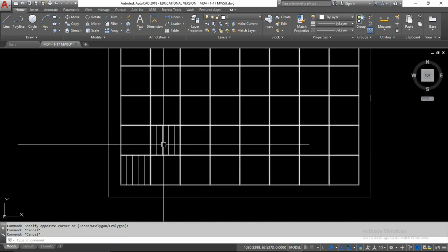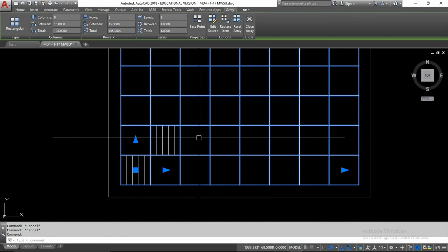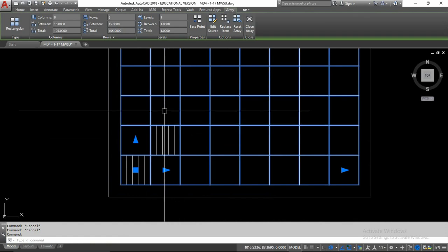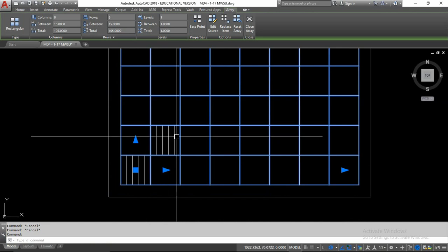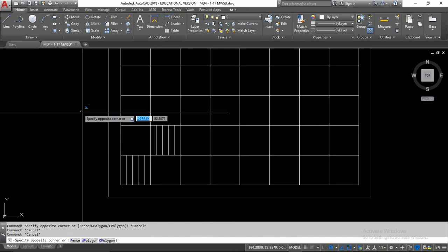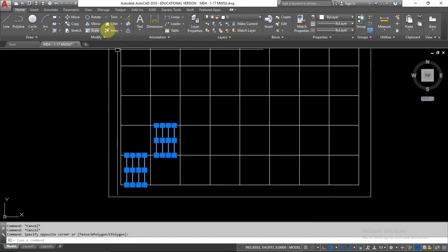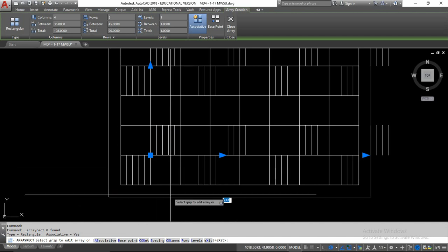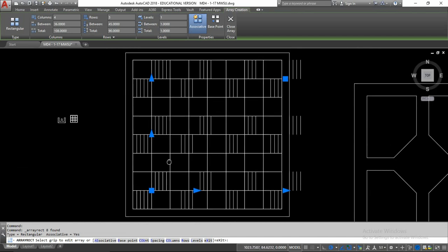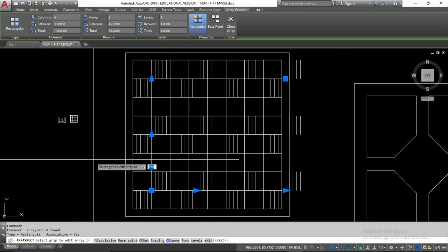Again, the reason is this isn't one square. Also it's not 64 squares. It is a locked or protected array. It is one array of those 64 squares. So that's why this blue window is not selecting any of those. But here's what I'm doing. I can go ahead and array this. Let's see if it works. See if my idea here, trying to save myself time yet maintain precision, will work.